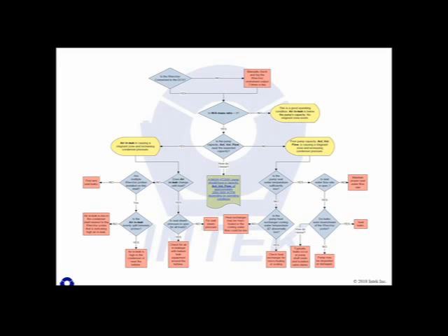Okay, thanks, Kathy. So let's start off. This is a new flow chart, and it kind of summarizes what we've just talked about. Yesterday, I showed very vivid examples of how air is stored in the condenser. I showed those performance profiles of tube bundle arrangements when we increased air in-leakage, and you were able to see the blue region grow out of the air cooler section as air in-leakage went up.